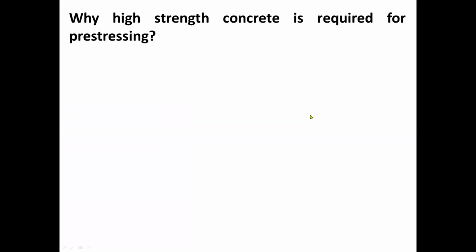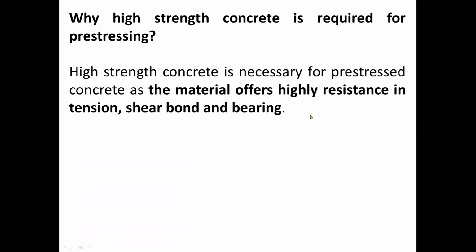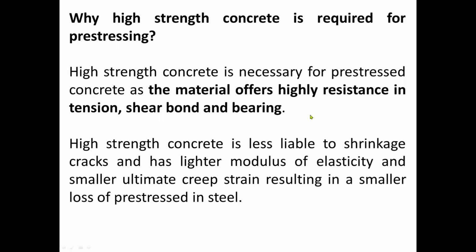Why is high-strength concrete required for prestressing? High-strength concrete is necessary for prestressed concrete as the material offers high resistance in tension, shear, bond, and bearing. High-strength concrete is less liable to shrinkage cracks and has a higher modulus of elasticity and smaller ultimate creep strain, resulting in a smaller loss of pre-stress in steel.